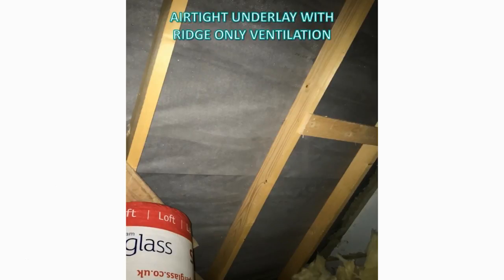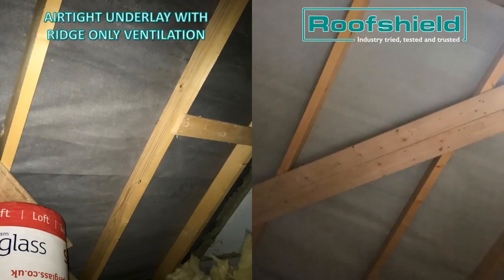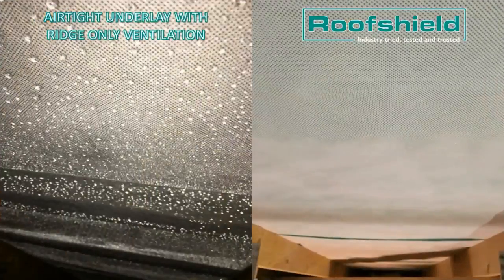At the time of testing, condensation was visible in the ventilated roof, where none was apparent on the underside of the roof shield under the same conditions. In close-up, the quantity of condensation present suggests the ventilated roof is not performing optimally.